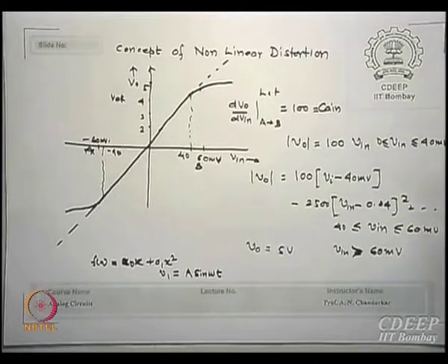What does that mean? In real life, I will see to it that I receive power only at omega, my fundamental. I may use what we call a tuned circuit there, which will pick up only the signal at omega. But what does it mean then? That the power, or energy, which has gone to 2 omega, 3 omega or n omega, I have lost. So the efficiency of an amplifier will keep reducing as non-linearity increases, is that correct? Because you will not get the equivalent voltage you would have got with linearity; some part of it is lost, is that correct?